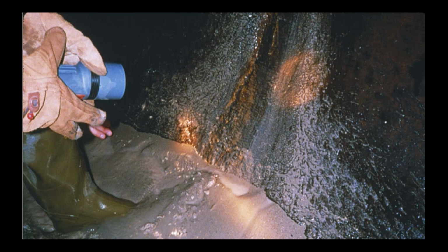If you were to inspect the dam and see soil deposits in the conduit, that would be a clear indication that you have erosion of the embankment material, short-circuiting and going through the joint into the conduit. Most times you will not see this evidence because it's being flushed out as water goes through the conduit.